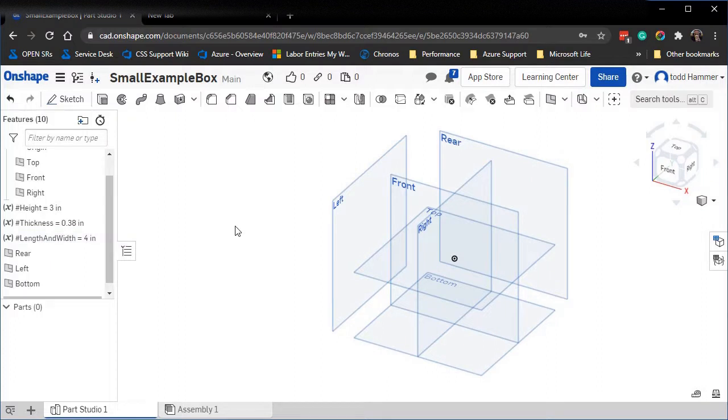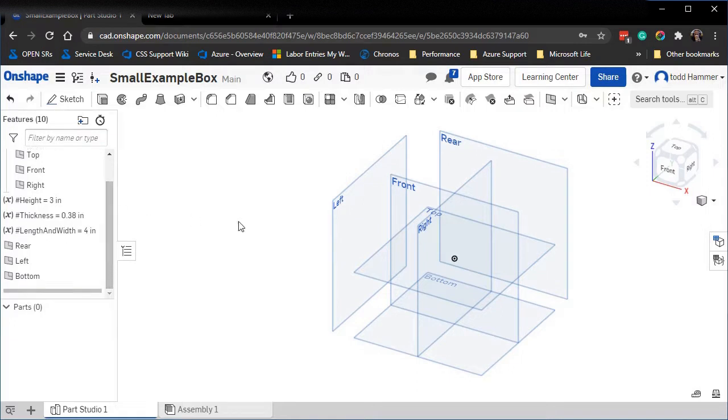So in this program, everything you do is going to start with a sketch. Okay, and a sketch has no depth to it, it's just flat. It's sort of a figurative thing, really has no thickness at all. It can't be measured in thickness, but after that, you're going to extrude that sketch in different manners and create your 3D parts. All right. So let's first create a sketch.